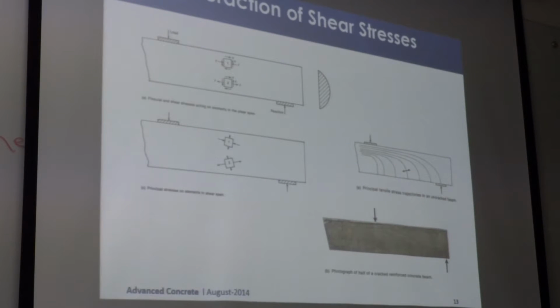Okay, if I put them together, right, I can move them, slide them a little bit like this. However, if I press them, I can't slide them now. This is shear friction. Axial force and friction have a relationship. So that means the shear is produced because of the friction between two materials, which is related to the axial force. So another shear comes in, shear friction, right? So shear friction, normal shear due to tension, principal stresses, and interlocking shear. So three shear components will be then activated, making it further complicated.